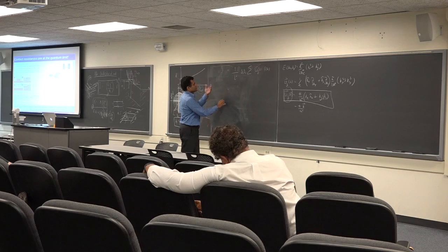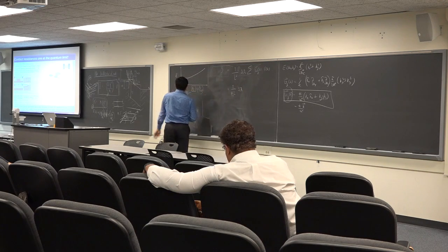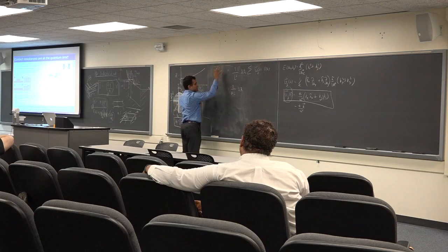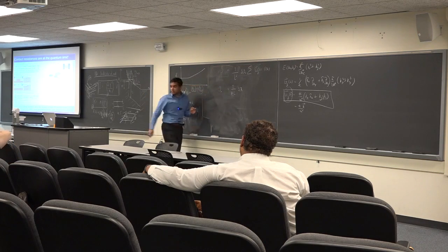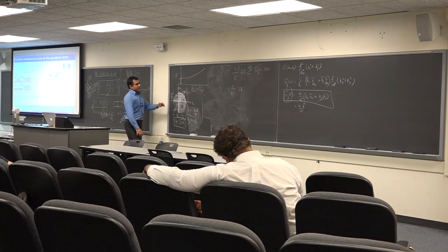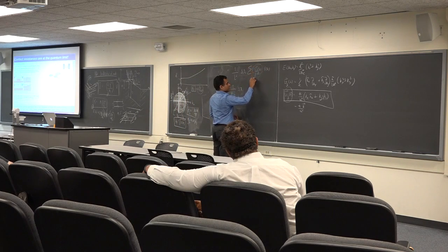And I will just do this. So here, again, you have W and L and your spin and valleys. But now I'm interested in the right-going current. So what I'm asking now is I don't want the whole vector. I want the current going in the x direction, from source to drain. If I ask that question, then instead of retaining the whole group velocity, I will only retain the x component of the group velocity.